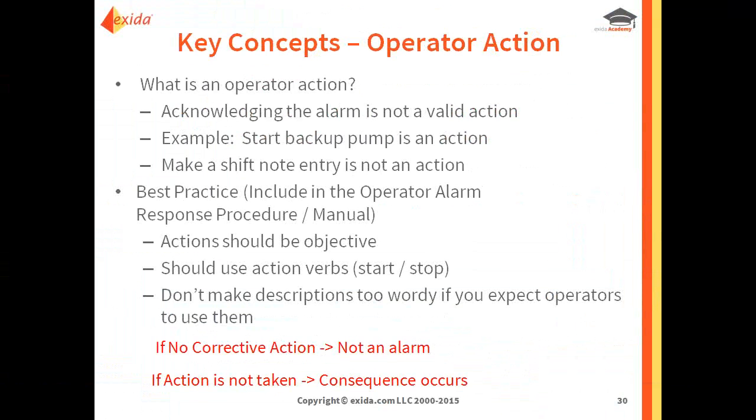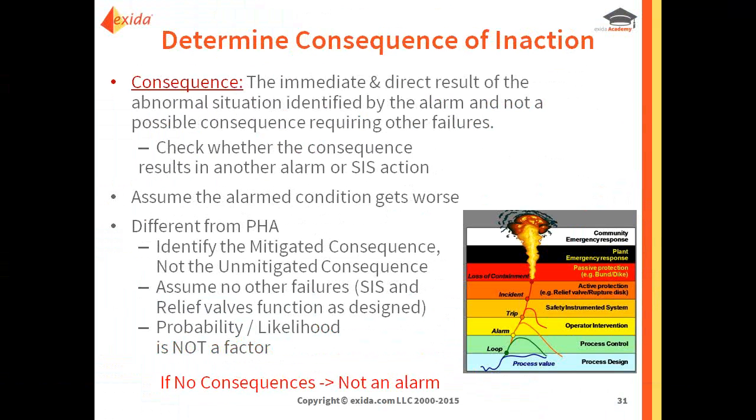For the purposes of rationalization, we're not interested in writing a manifesto or a book. We want to keep it short, to the point, action verbs, particularly if we want to take this information and then turn it into an alarm response procedure, which is a best practice and a good recommendation. So we want to make sure that whatever information we're documenting here, if we're going to turn around and make it available for the operator, we need to put it in their terminology, in their terms.